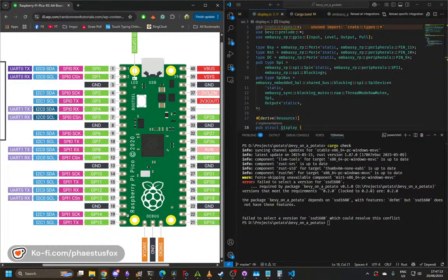Do I rely on this to 4? I'm going to plug it into the one that says 15 on my breadboard, because that's where it says it'll be. Pin 11. Okay. So next pin is a reset. Okay, reset's orange. Reset is pin 10, which is one up from 11.